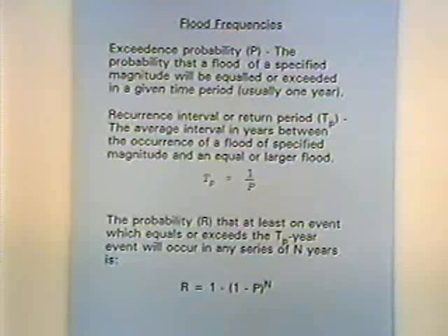And so we design bridges and culverts and inlets to storm sewer systems, and we design storage capacity and detention basins and all types of structures and management strategies. We delineate 100-year floodplains to keep people from building houses too near the river. All of these things we do for a given exceedance probability that's specified in the criteria we're using.